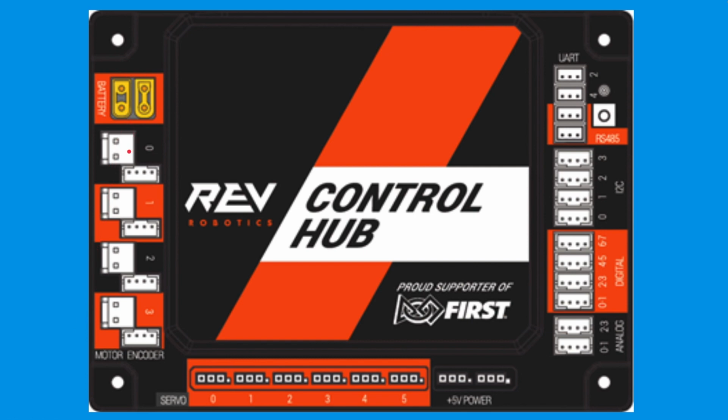There are two ports. There is one for power, this big one right here with 2 prongs, and one for an encoder, which is here with 4 prongs. We'll go over encoders a little bit later. So you will plug in your power cable right here and your encoder cable right here. And note the number that is right here. This will be important. This is port 0, this is port 1, this is port 2, and this is port 3. You want to note these numbers because they will be used when you are configuring your robot inside the driver station app.